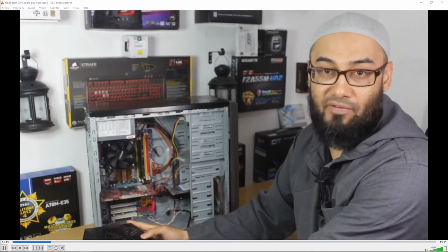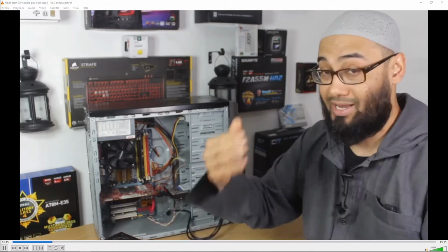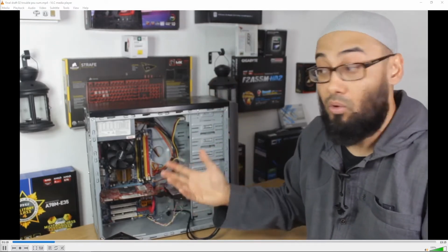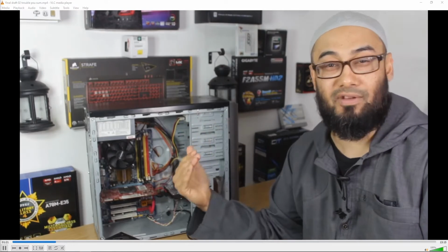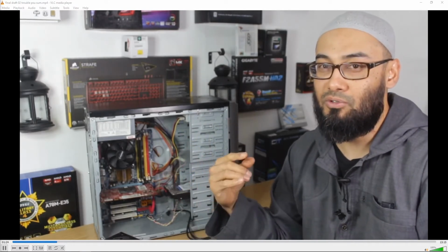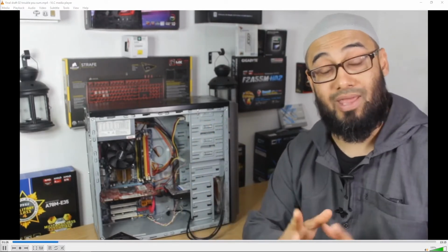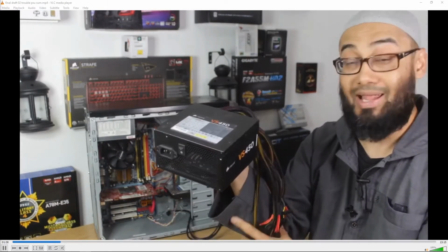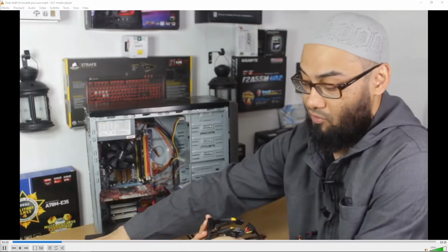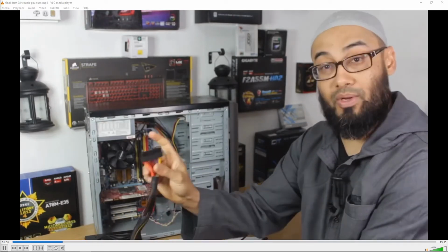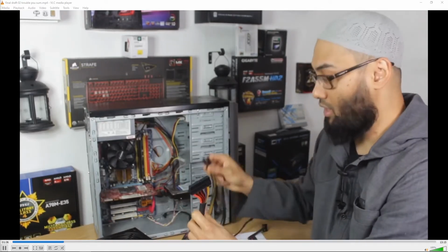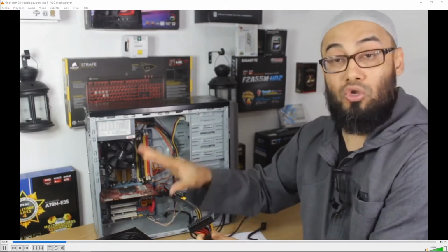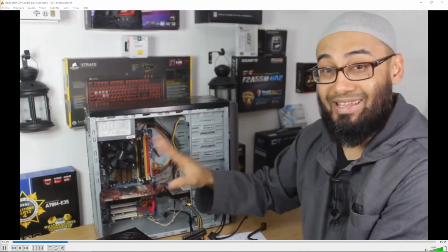But if it's a new device and you don't know the history, and the client or the owner of the computer doesn't tell you or doesn't remember what happened, or if you've transferred components from a different case, it might be difficult to know which one to start with. In reality, you should actually do both. But most of the time for me, I have a power supply lying around, and it's very easy for me to just unplug the 24 pin mains and also the 4 or 8 pin for the CPU, and just plug in a good known working power supply, and I can quickly test that.